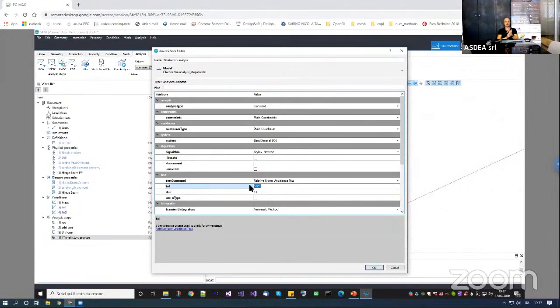There is only one problem. When you're using very tiny time steps, for example because you're doing a very nonlinear dynamic analysis, and the first error at the beginning of the step is already very small, it will be very difficult for OpenSees to lower that value by 1000 times. So you have an advantage sometimes, but with very small time steps, the relative norm is not advantageous. In fact, in the next days we will code something for OpenSees which is a mix of relative and absolute test. That would be the best choice.